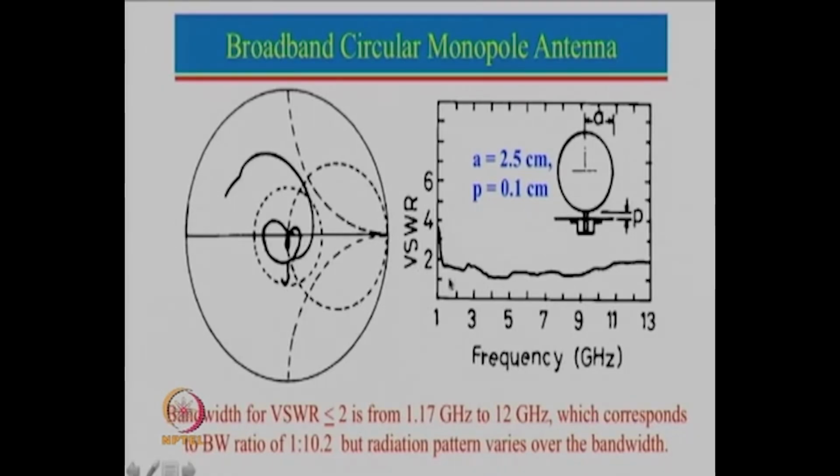So that is where it will come. Just to give you an idea, but the effective length will not be just lambda by 4; the formula has to be used, which is H plus R equal to 0.24 lambda. If you do that, you will get very close to what we have got over here.